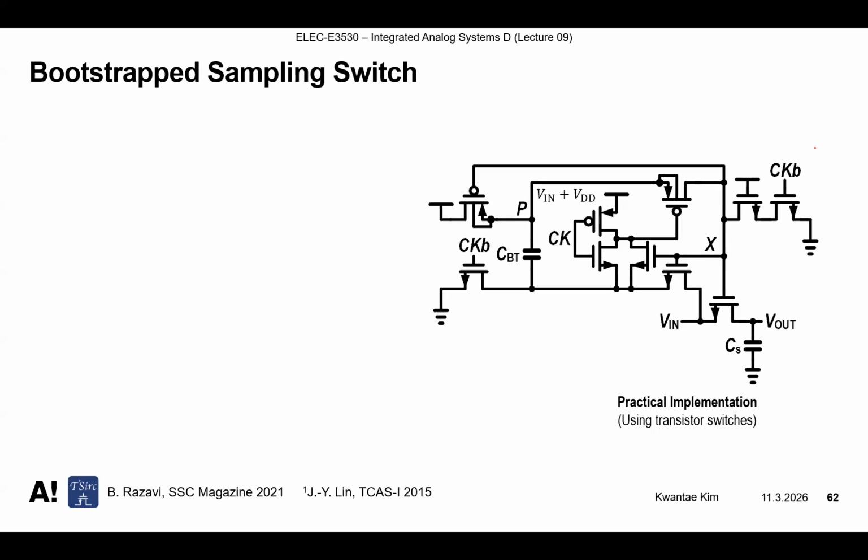You can check the transient simulation waveform from exercise 7. If we connect 2 transistors in series, then there is a resistance divider. If we set the transistor sizes the same, then even if there is 2 times VDD, the middle node is almost close to VDD, such that VDS of each transistor is ensured to be as high as VDD only.